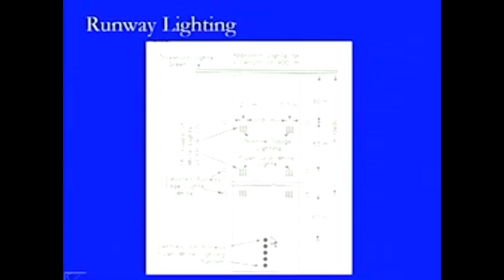and these are provided symmetrically on both the sides with respect to the center line. Here we can see the center line runway flush white lighting system which looks like this. And here we are also having the edge light systems which are elevated lights which define the end of the runway in the transverse direction. And these lights, this type of elevated lights which are white in color, are provided for a distance of 1080 meters from the end of the runway.